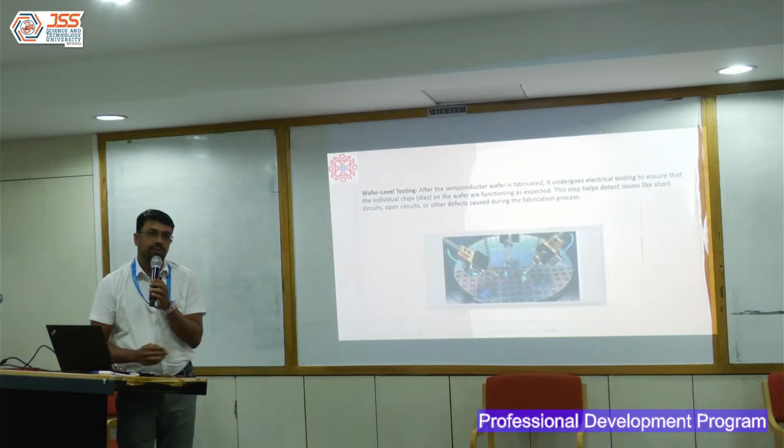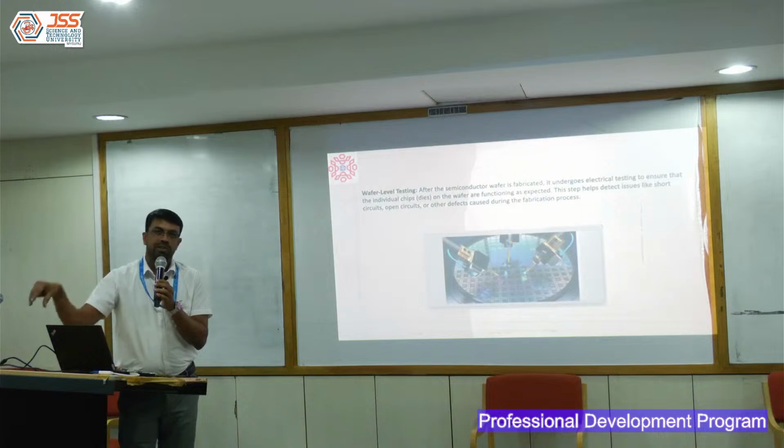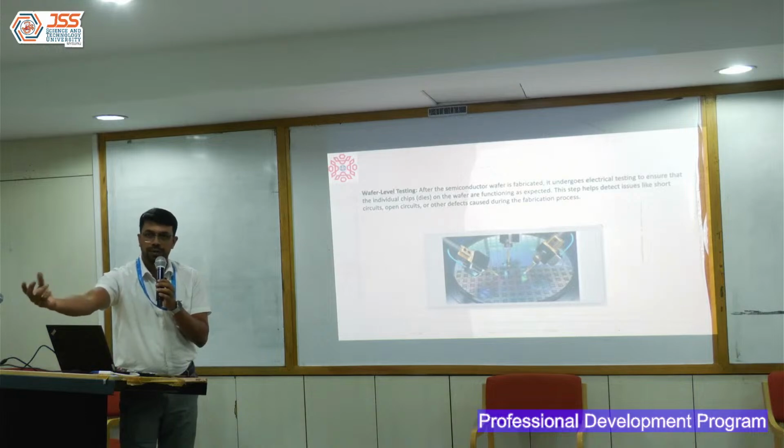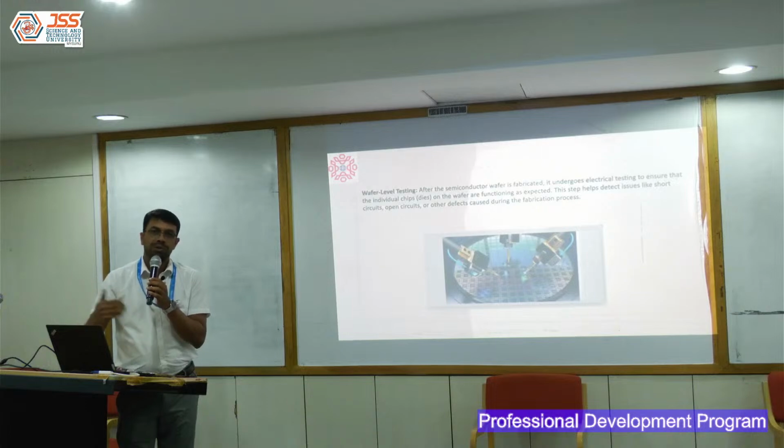We have to load this pattern to that ATE supercomputer, and it is interfaced with a robotic arm, which basically picks each die, keeps it on the board, applies the pattern. If it is a pass, it puts it in one bin. If it is a fail, it puts it in another bin. Human interaction is only with that machine.